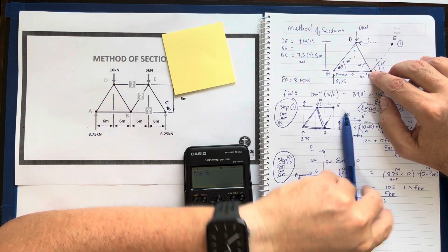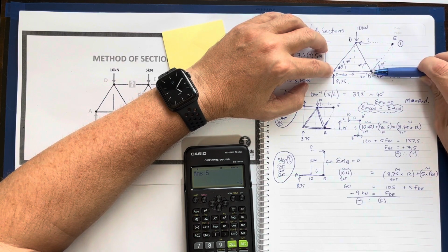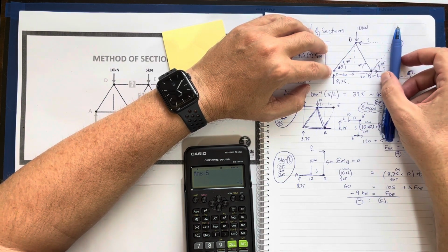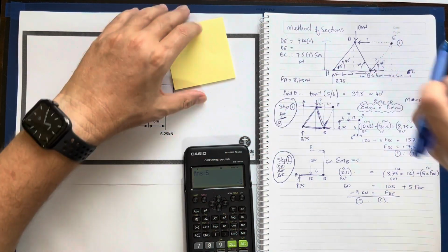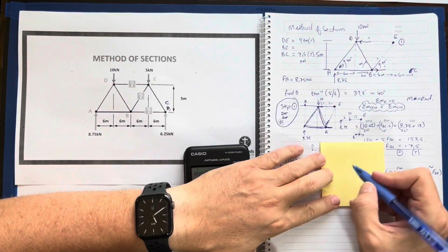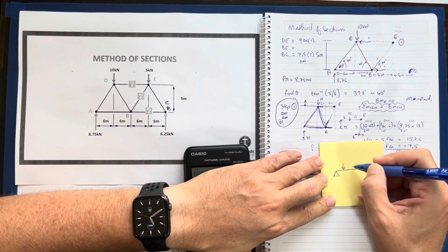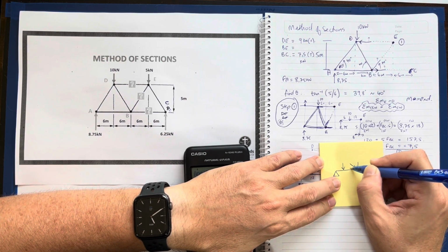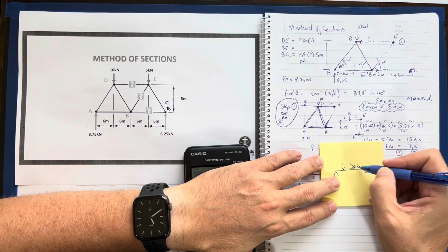And I want to pass a beam through that point where it connects so that I can work out either its vertical or its horizontal in order to make a beam. Because in all the beam calculations that we do, we always resolve angled forces to be the equivalent vertical or horizontal. We never ever leave them at that angle.